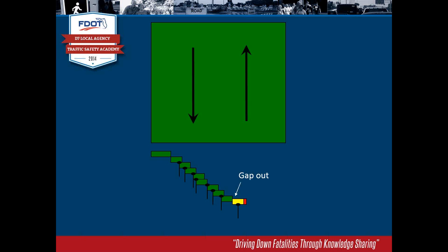And you've probably seen this, I know I've seen it many times: you arrive at the loop just after the last millisecond of green. You arrive just at the beginning of yellow. And you're not going to be detected. You're not going to be extended because you got there after the last second of green.